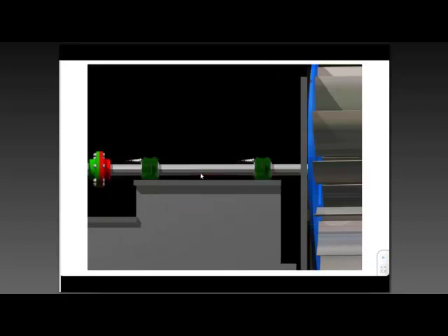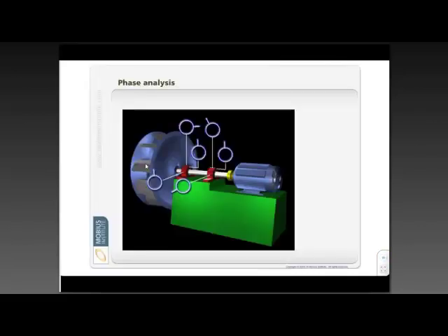And we can, again, do phase readings by comparing the vibration in these axial directions on the bearings and see what's happening. Now, this is a bit complicated, but I can see 90 degrees phase shift at this bearing, 90 degrees phase shift at that bearing. These aren't in phase, but when I compare this axial reading to this axial reading, they are in phase. Now, I might be throwing you in the deep end, but what I want to just show you is that these phase readings are easy to take. If you've got a two-channel analyzer, very easy to take, and they confirm your concerns.